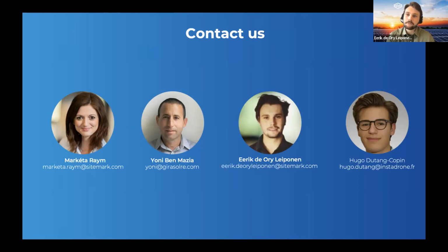So what anomaly types can be spotted on the platform with this quality data? Oh, this is a question for a whole new webinar, I would say. So I will say just briefly that the platform can detect almost all types of anomalies that can be detected on solar modules, from hotspots to diodes to string issues, single diodes, double diodes, whatever, PID actually, which is very important to detect if you have a concern of this kind of phenomenon on your modules.